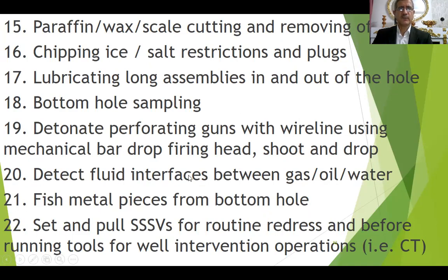Then detect fluid interfaces. If we have gas, oil, water in the well, we can know the interfaces between them. Depending on the weight of the tool string, if the weight drops, then we have what is called the interface, gas-oil contact or oil-water contact.